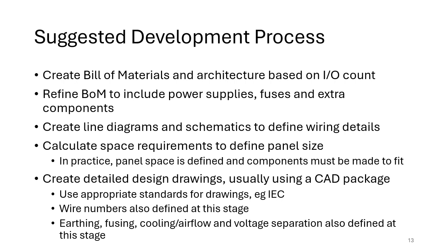And then you would move on to create line diagrams and schematics, which would give you better definition of what the wiring details would be. So for example, it's all very well to show a single line connection to an input device, but ultimately you need to define how that input device is wired. Is it 2-wire, 3-wire? Do you need a positive supply? Does it just need a single wire to the I/O? Do you need grounding and earthing and so on? So there's a lot of details that might be required when you actually start working on these schematics.